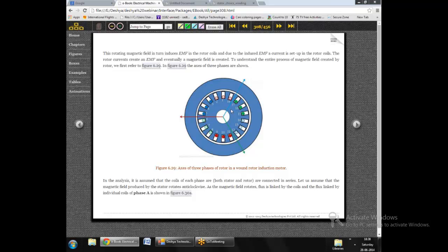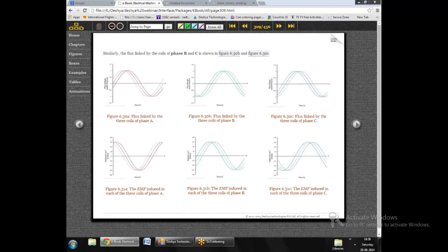So if we place this rotor inside a stator which is producing 4 poles, then the machine will not be able to produce torque because this winding is capable of producing only 2 poles. So now here comes the major difference between the cage rotor motor and the wound rotor motor, that the cage rotor is able to adapt to any number of poles that the stator is producing, whereas in case of a wound rotor motor, one has to wind the rotor accordingly and produce the specified number of poles.